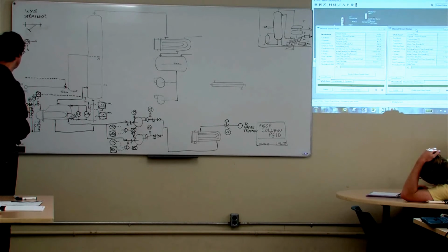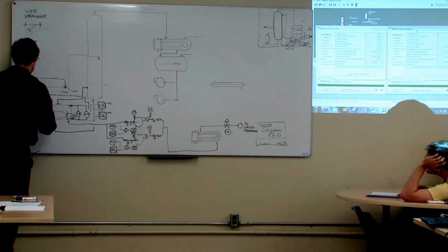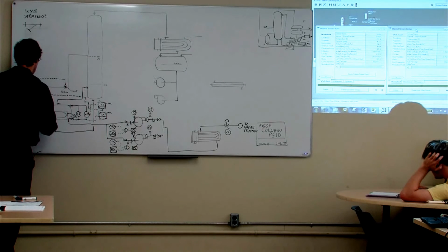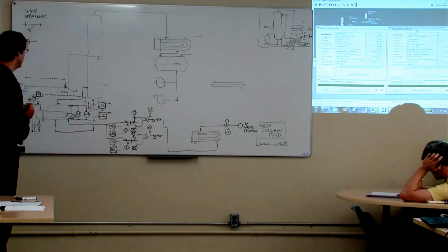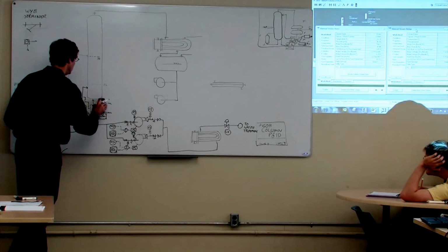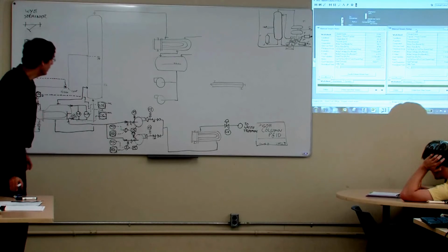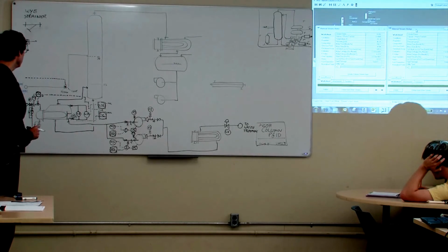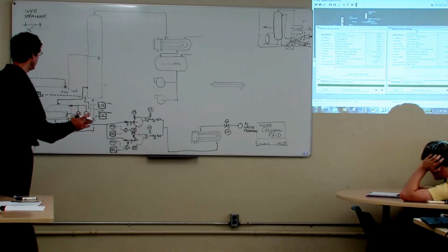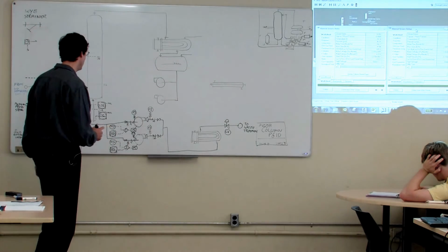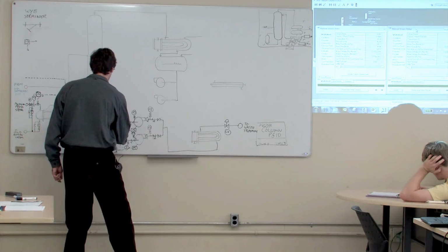Like that. And if you want to, you can write the letters SP to indicate that that's a set point going into the flow controller, but you guys know that that's what's intended anyway. Okay, so that means that we're left with the temperature indicating controller that's got to go over to that valve, and so we just send a hard wire over there.